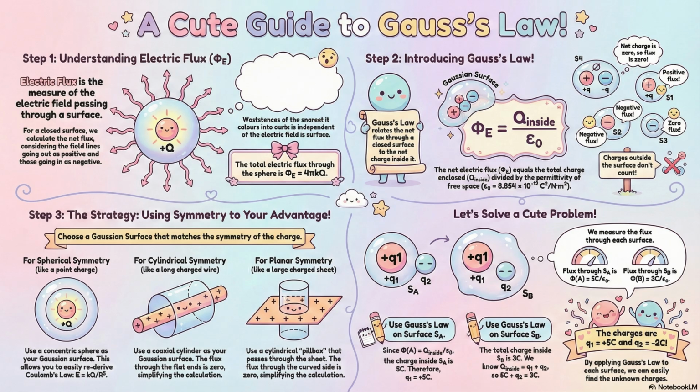Okay. The Arrhenius equation in our sources makes this very practical. If you can reduce the capacitor's operating temperature by just 10 degrees Celsius, you can roughly double its expected service life. Wow. So thermal management is everything for these things.